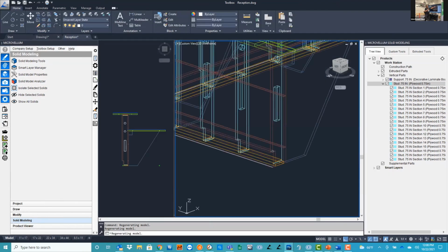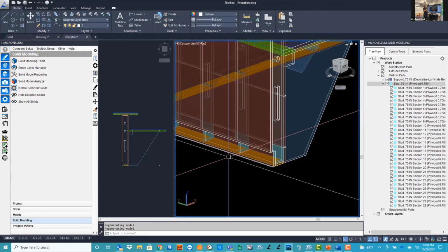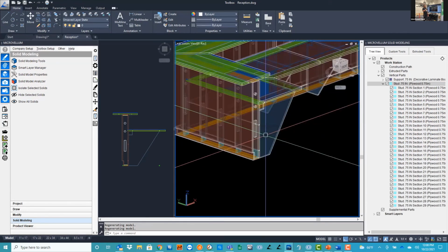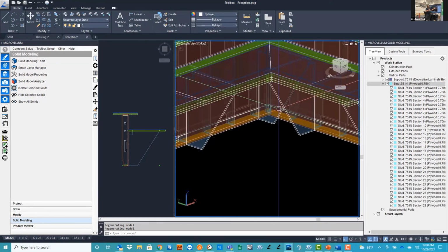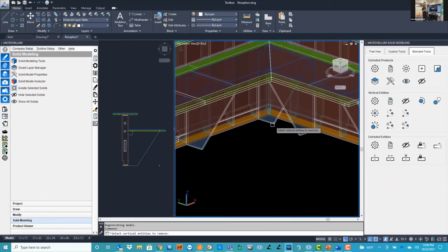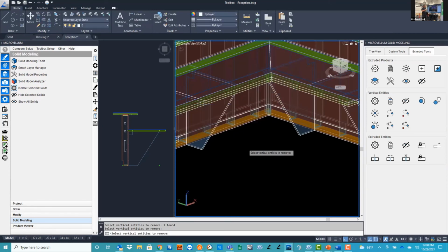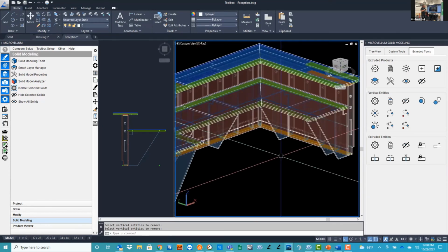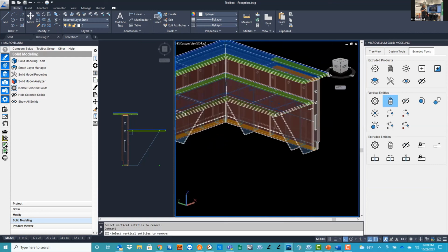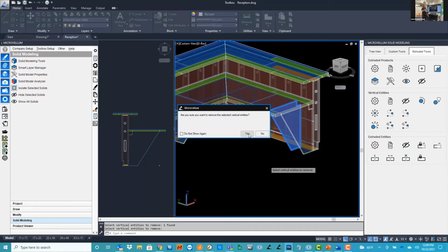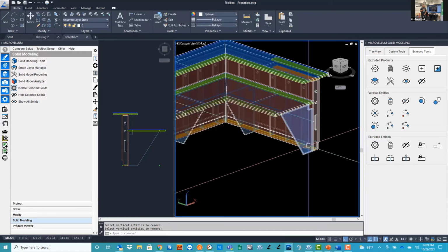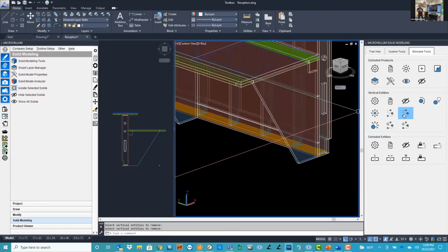There are additional tools that we have under the extruded tools that will allow us to do other things to manipulate these parts. So I'm only going to show you a couple. I'll use one to erase an extra component, and I'll get another one over here. I'll erase this other double up support. And then I'll use move part command, and I'll just move this over a couple of inches. There's tons of others. We can do things like replace a part.